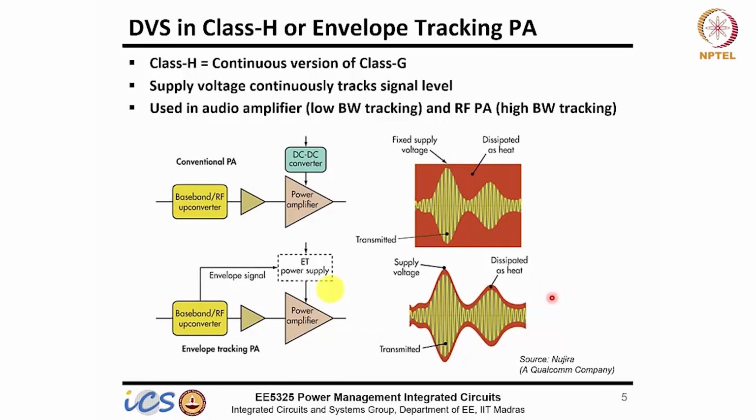Or in another way, you can think about it in terms of an LDO. If you keep the dropout voltage fixed, irrespective of your output voltage, then your losses will be fixed. You can always achieve a high efficiency no matter what the voltage is. But if you keep the input supply fixed, at a lower output voltage, dropout will increase and your efficiency will drop.